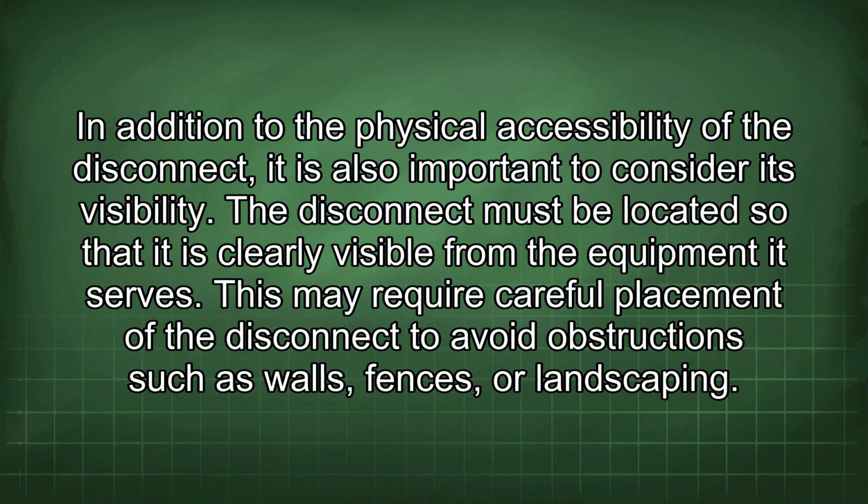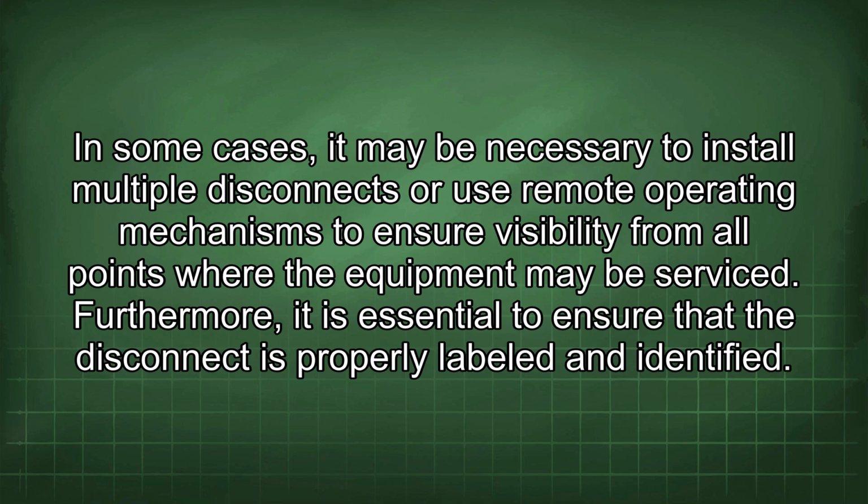This may require careful placement of the disconnect to avoid obstructions such as walls, fences, or landscaping. In some cases, it may be necessary to install multiple disconnects or use remote operating mechanisms to ensure visibility from all points where the equipment may be serviced.